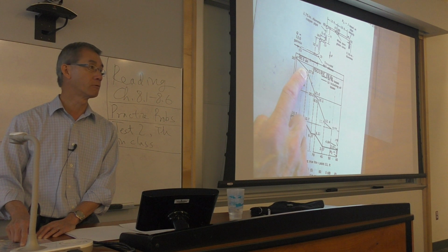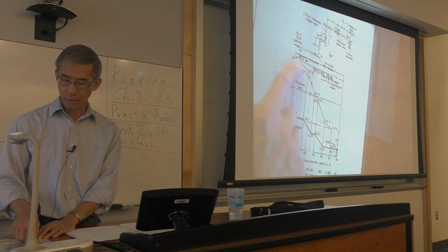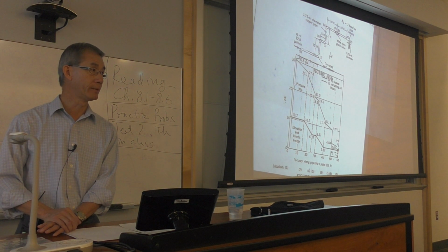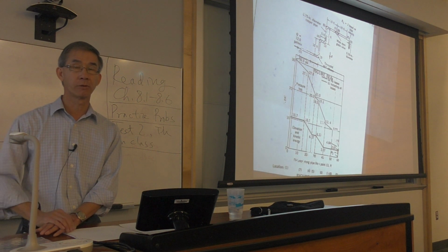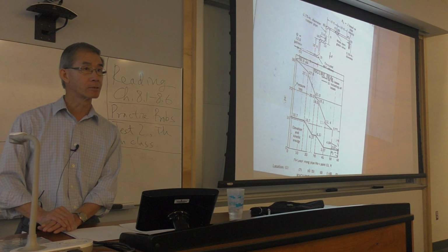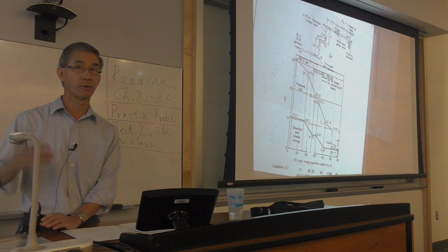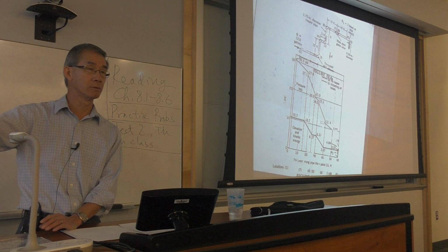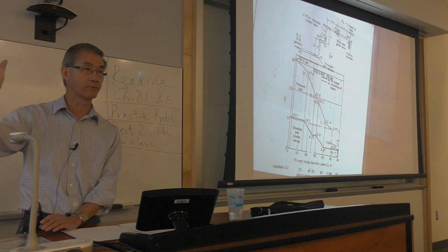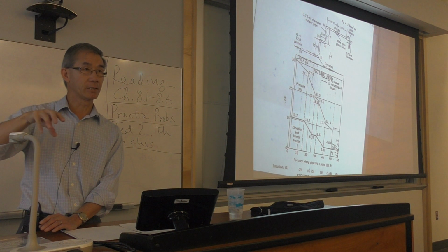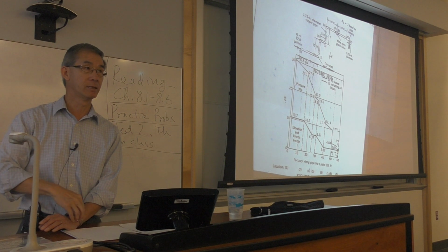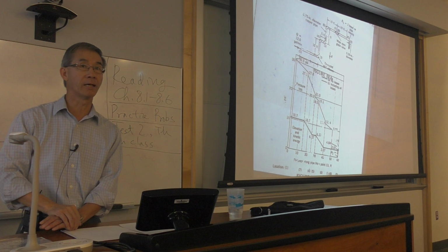This slope is purely due to friction. Adding them all together, working back, you need at least 30 psi to push all this water through, right? So municipal water supply coming from town, if you live in an apartment or a duplex, whatever, there's a water supply that's in the yard that you have to tap in.